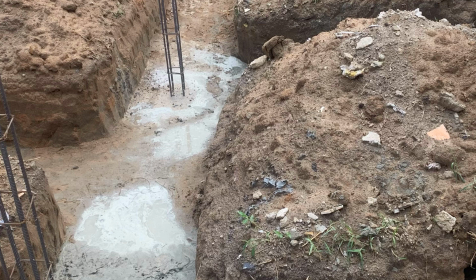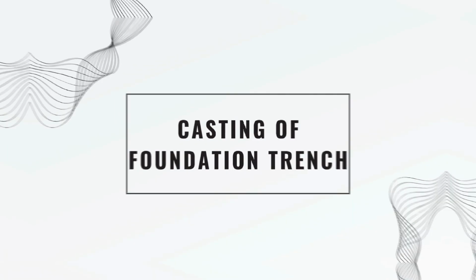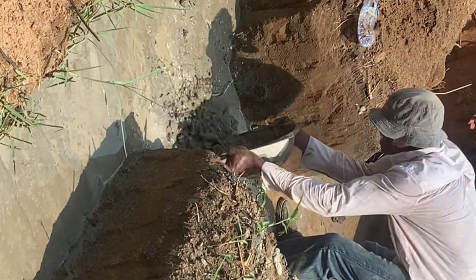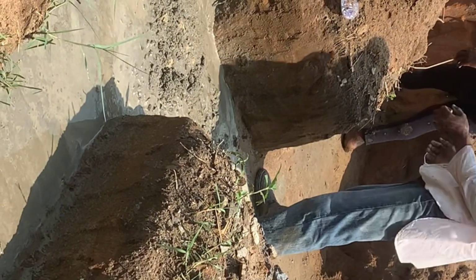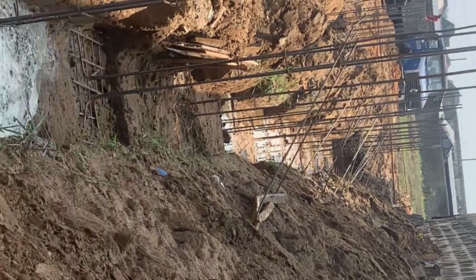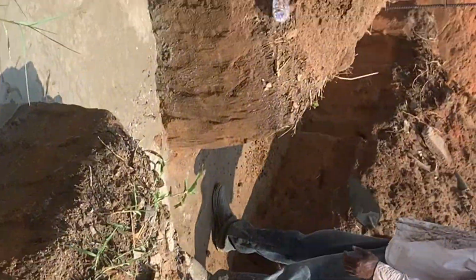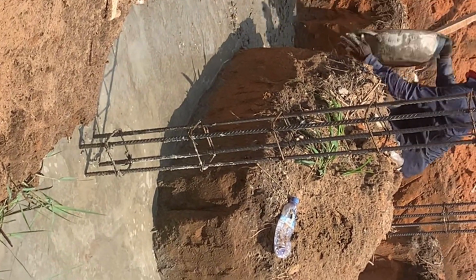Now, the next stage we are going to be talking about is the casting of foundation trench. Once the column base casting has been completed, it is time to cast the whole foundation trench. The thickness of the concrete required is gotten from the structural engineer. Please note, care should be taken to ensure that the proper mixed ratio from the structural design details is adhered to, and during placement of concrete, the concrete should be placed at a level closer to the foundation.